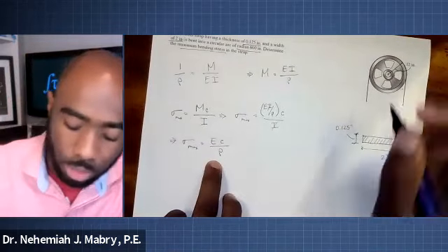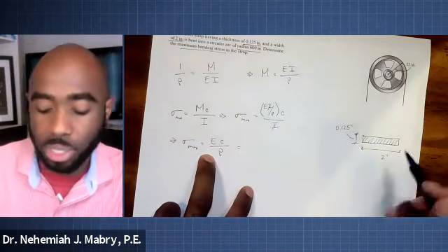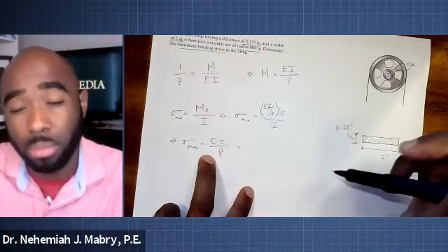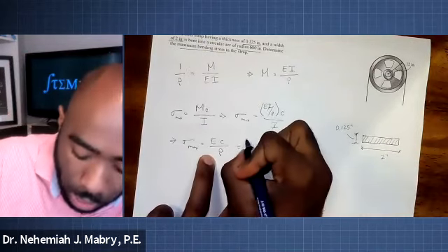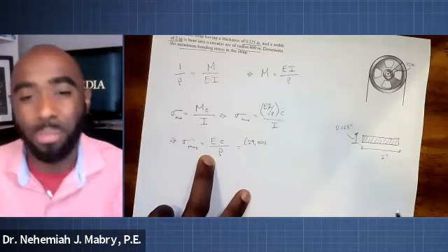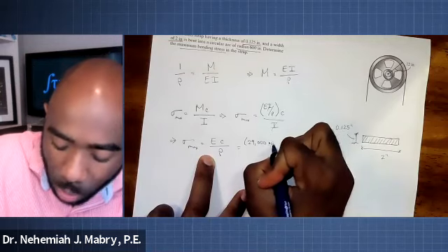Well, E, for starters, is going to be the modulus of elasticity of this material. What is the material? Well, the material says that it is a steel strap. So we know right off the bat that one number that I said you can remember in terms of properties, 29,000 KSI, you can go right there in terms of the E.